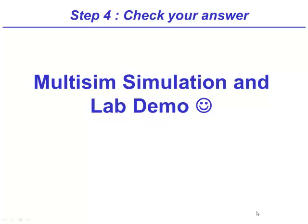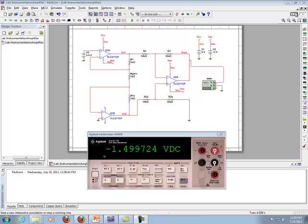All right, now for the Multisim simulation and the lab demo. I'll do the Multisim simulation. Amir is setting up the circuit right now for the lab demo. Okay, so here is my circuit, which I've set up already in Multisim. Some points to note. I have 3 TLC277s, but 2 of them, U1A and U1B, are from the same package in Multisim. So when I power up one op-amp in the same package, notice how the rails on the other op-amp are already automatically connected.